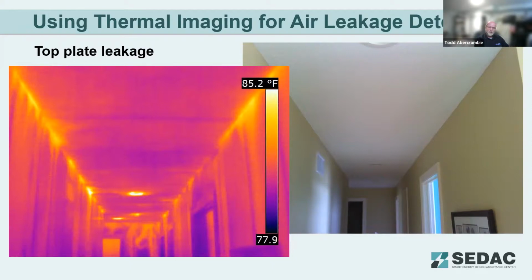It was taken in the summer with the blower door running, and so you see all that hot air coming down through the top plate, down through the interior walls, and then through light switches down into the basement, all kinds of places. So getting top plates sealed during the new construction phase is much easier than digging through insulation later, trying to seal top plates.